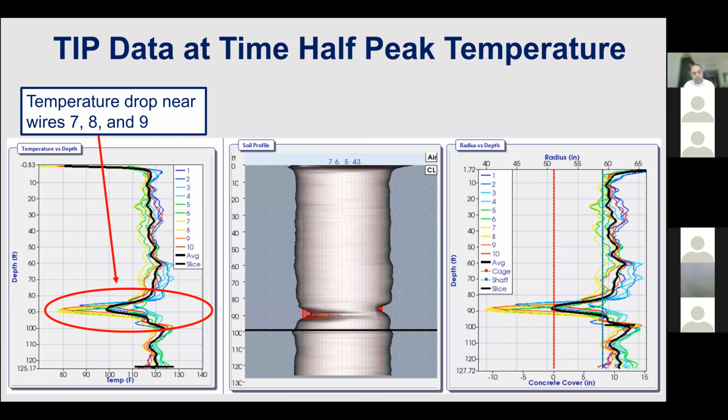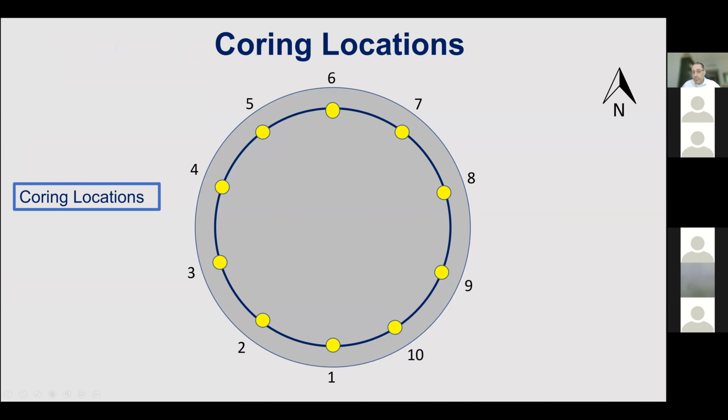around the cross section, and can tell you whether it's only limited to the cover or it extends within the concrete, within the reinforcement cage. In this case, it extended in the concrete reinforcement cage, and this was not acceptable to the client, and they decided to do more coring. And of course, because they thought this was the contractor's problem, they forced them to do many cores, to make sure that this problem is not extensive.